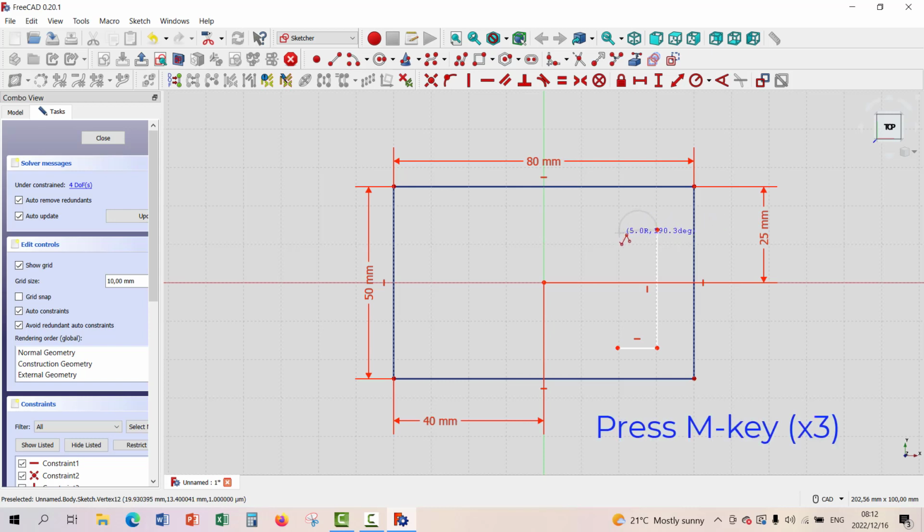We do something like this, and go down, connect. Now you'll see we've got 5 degrees of freedom again to go and fix. The first thing we needed to do was make sure that the rectangle was sorted out, so it's fully constrained. Now we need to constrain this one. So let's see if we can do that.